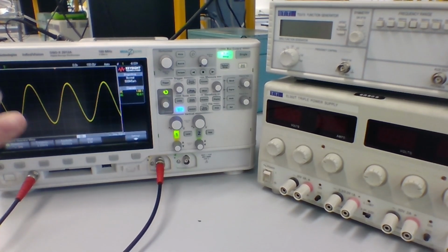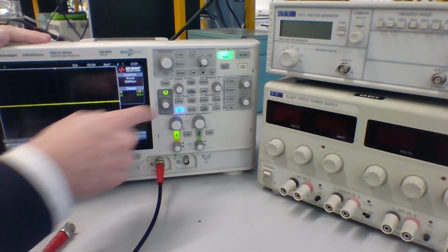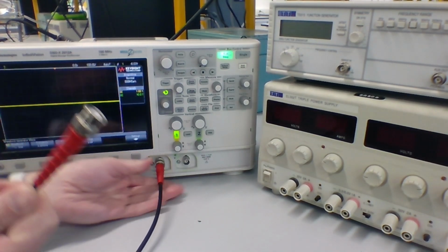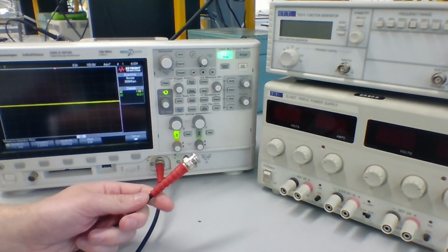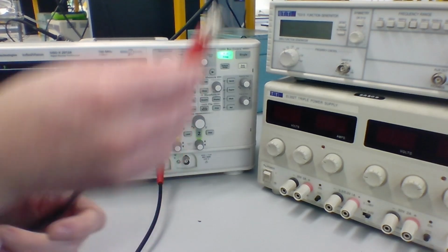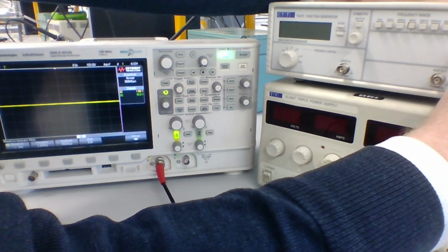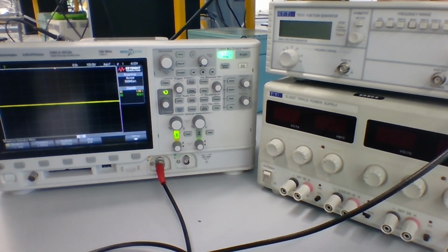So we're going to also use this function generator. To connect that up, we're going to disconnect from the oscilloscope, turn the wave gen off, and I'm going to connect the BNC connection, one end in channel 1, the other to one of the outputs of the function generator. By default, I'm going to use the right-hand one, which is a 50 ohm impedance connection, which is what this cable is. So I'm going to connect into that. To turn this function generator on, there is a switch on the back of it. You'll have to fiddle around to find it a little bit, but it's on the back of the function generator.